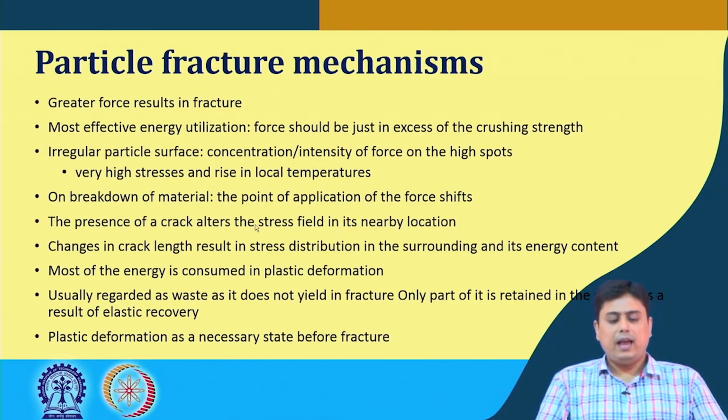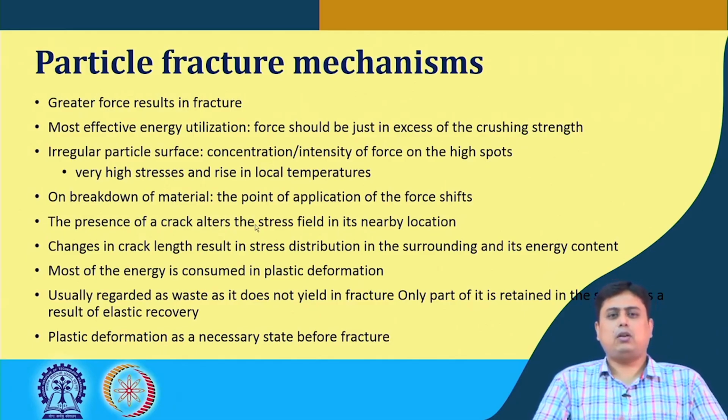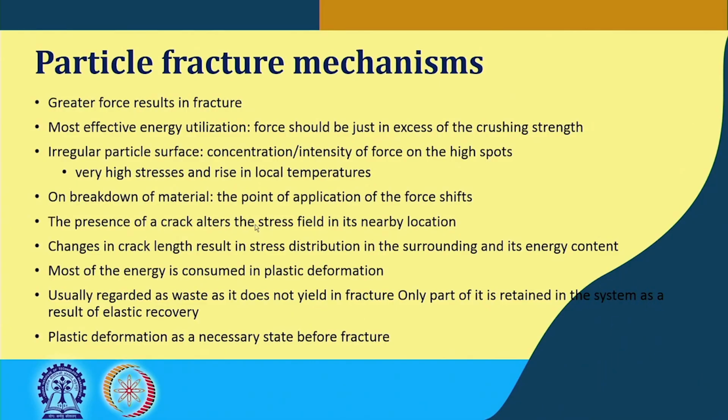We were discussing particle size reduction, and in particular the particle fracture mechanisms. We have now understood the ways in which particle fracture can be introduced. There is an elastic limit, and we have to exceed that elastic limit to introduce the fracture. Due to the irregular surface in realistic cases, the applied force or intensity has its stress distribution on the surface of the solid particle.